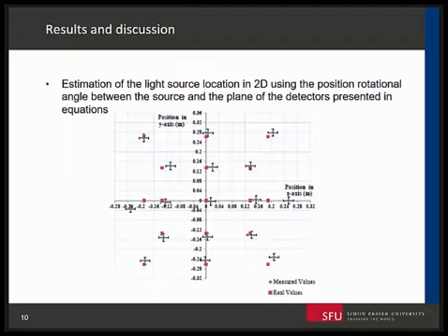And then finally, we were able to use our equations and our measured photocurrents in order to back calculate the azimuth of the source of radiation. For this one, we placed our source of radiation in 16 different positions with respect to the pixels, passed them through the algorithm, and then calculated the azimuth angles. As you can see here, the difference between the positions based on the measured value and the actual value is quite nominal.